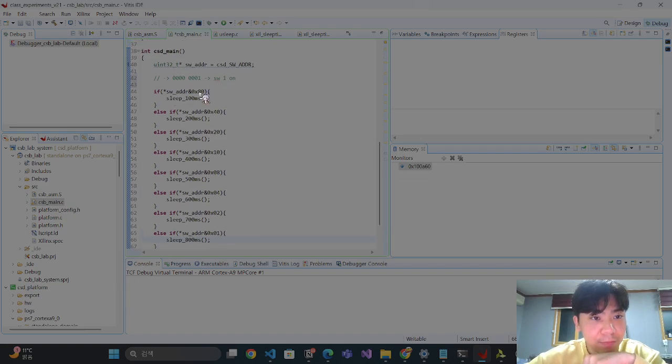In the if else statement, there is a logical AND statement. Hex 80 in binary is 10000000, and hex 80 means switch 7 is on.